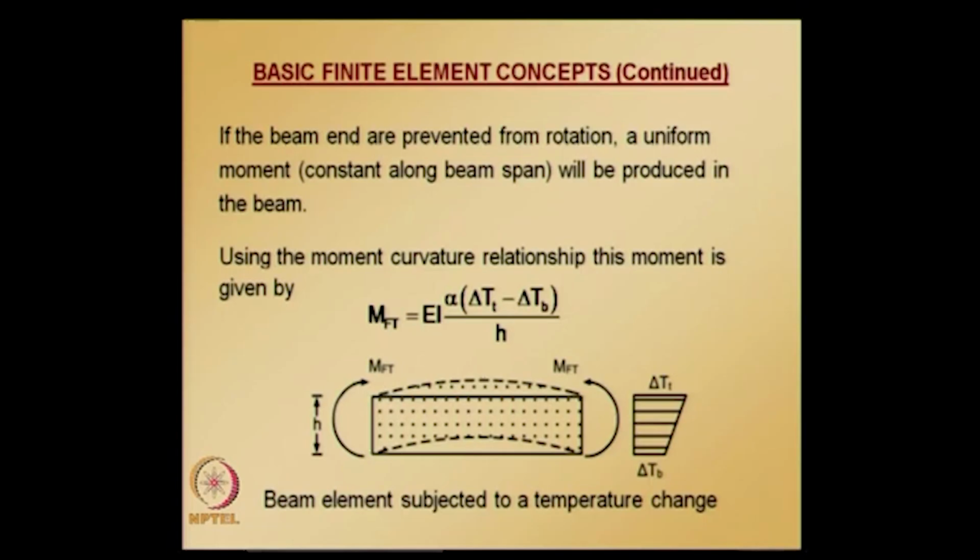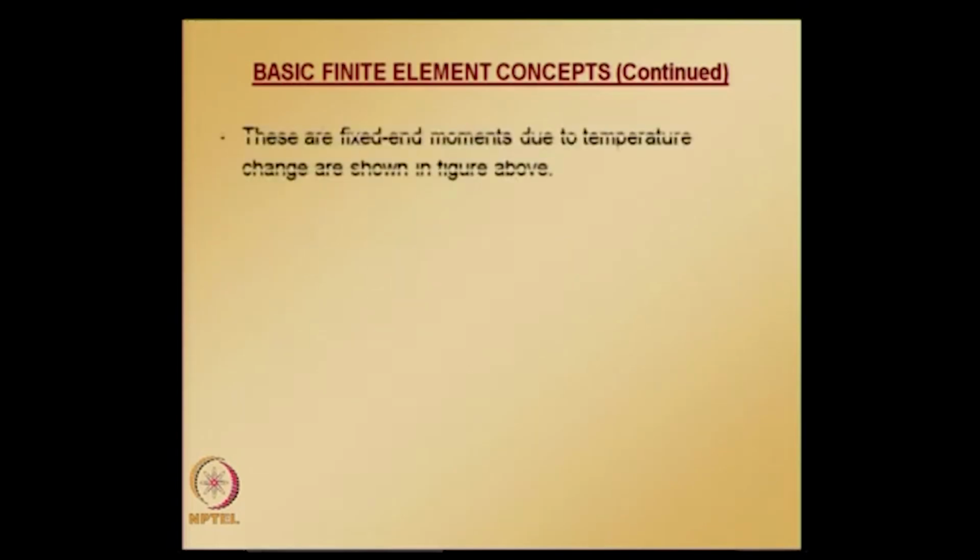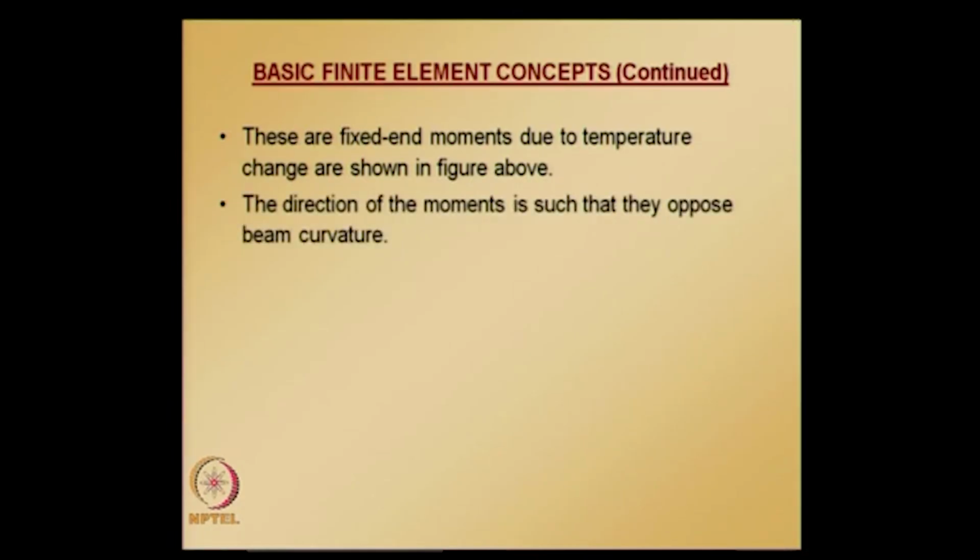and with the fixed end moments, the remaining analysis is very similar to the distributed load, and the equivalent nodal load vector is equal and opposite to the fixed end forces and moments.